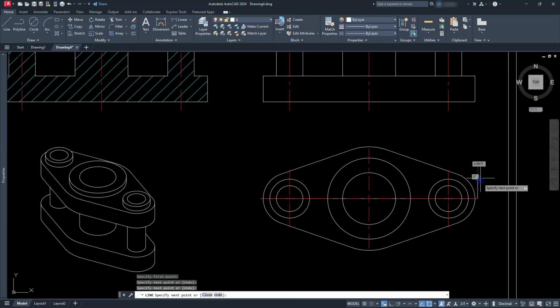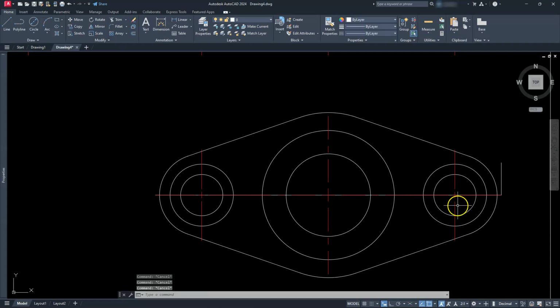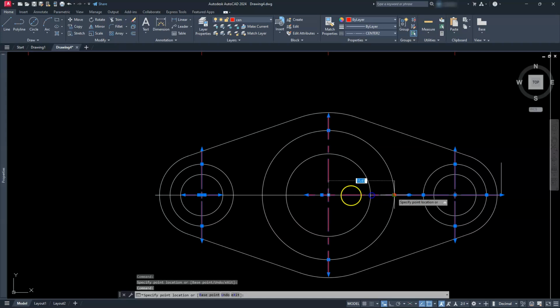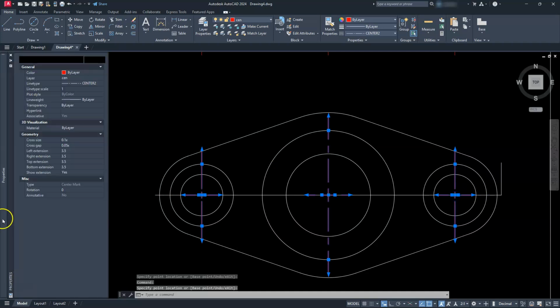And then I'll go up a little bit, right? Let's go ahead and select each one of these center marks here. And then I'll put the squares on the inside of these squares, right? So this is all that little tedious stuff, just to make sure your drawing comes out correctly. And a lot of times, anytime you're doing AutoCAD drawing, the drafting portion, as far as putting dimensions on and things of that nature, usually takes you the longest time of any. All right, so with all 3 of those still selected, I'll use my properties window and I'll find the extension left and right, and I'll make both of these numbers 0.